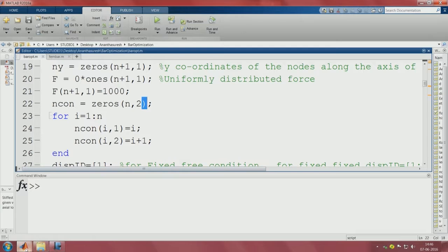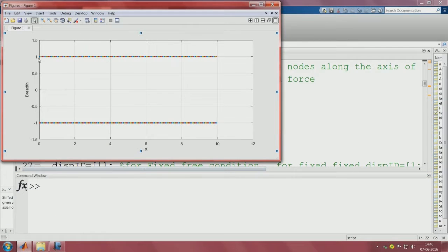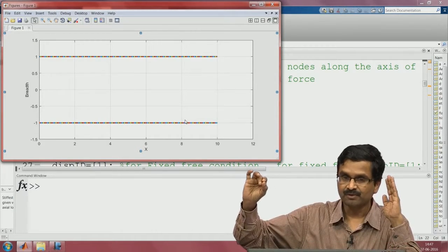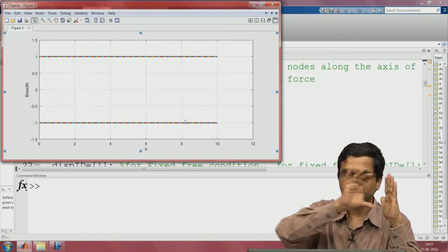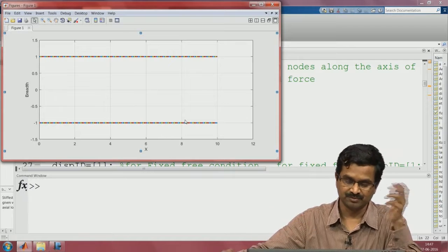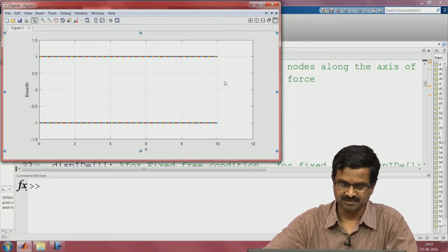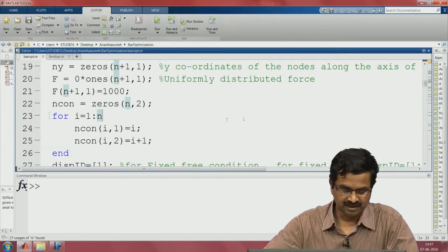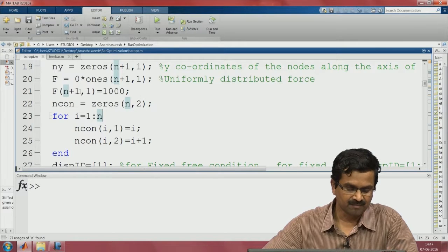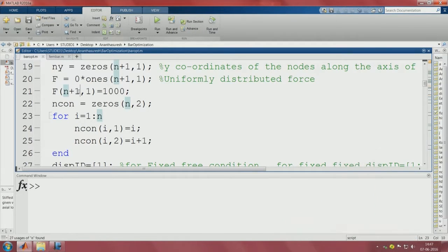Again it is running, it finished, we got a solution like this. So, here it is uniform cross section. That actually makes sense. If you want to make the stiffest structure for a fixed-free bar with a point load at the right end, the best solution is simply uniform cross section. That is what we got with the volume that we have. Now, the volume is 2 times the length times the depth that we have specified for the cross section. So, once we have this, we can play with it. Instead of applying there, in total we had 200 elements. Let us say I apply somewhere, as we had here, at the 50th node.